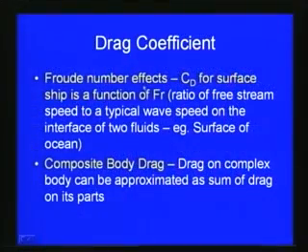So, now another important parameter as far as the drag force or the drag coefficient is the Froude number. Say for example, if we consider a ship, the coefficient of drag for a surface ship is a function of Froude number, that means the ratio of free stream speed to a typical wave speed on the interface of two fluids, for example the surface of the ocean. Then we can show that depending upon the Froude number, the coefficient of drag changes.